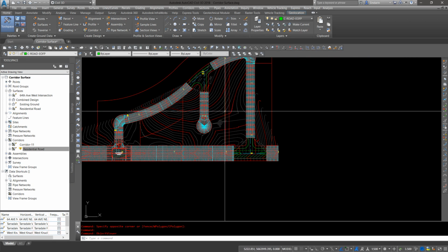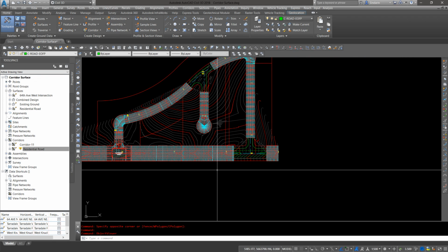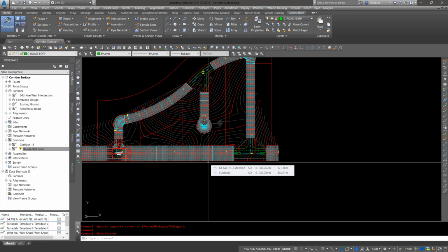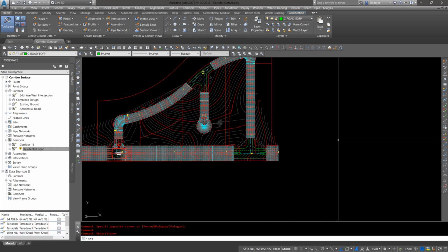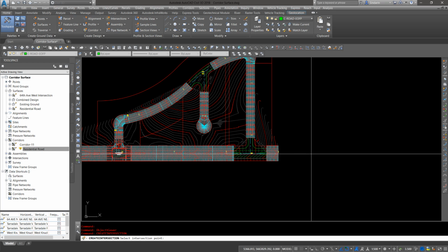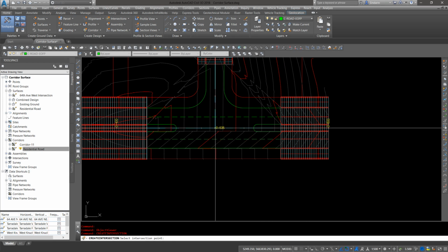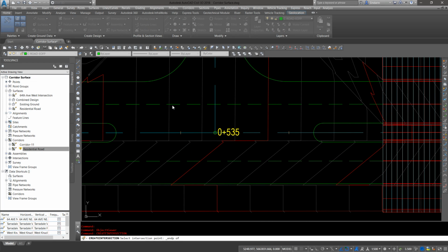And then I'm going to go ahead and build the second intersection the same way that I built the first one, the same numbers, 9.45, 4.25, the same radiuses. It's the same settings, the same two roads are connected. So again, create intersection at this point here.